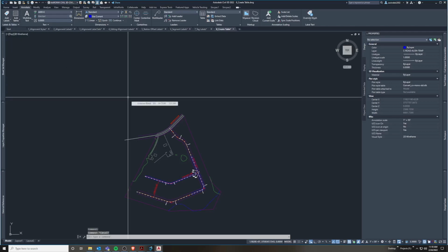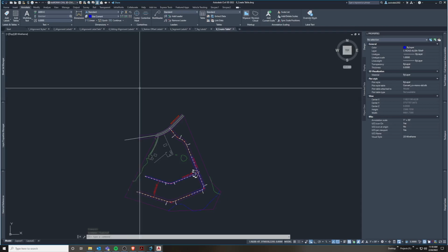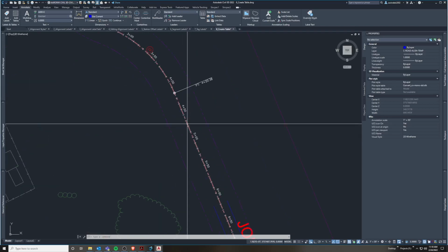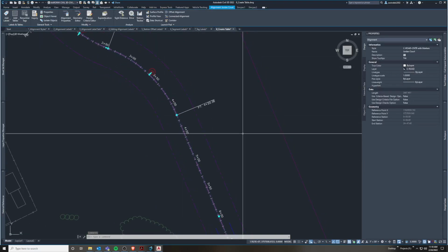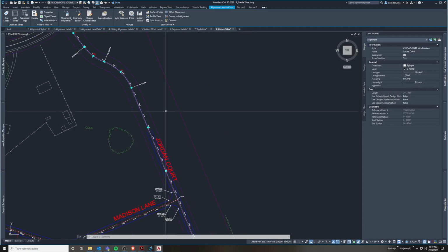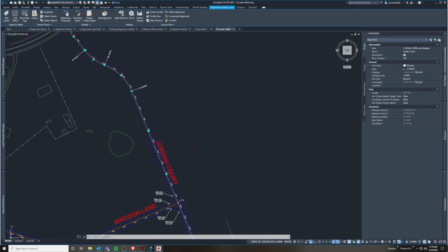So we'll go into page 128, and we're going to start creating them. And the tables are dynamic. So when your alignment changes, the labels change, the tables change, they all change together. So that's part of the dynamicness. You can choose them to be static if you want, but generally I make them dynamic for obvious reasons: I want them to update when I want them to update. So we're going to create a table for these tags.